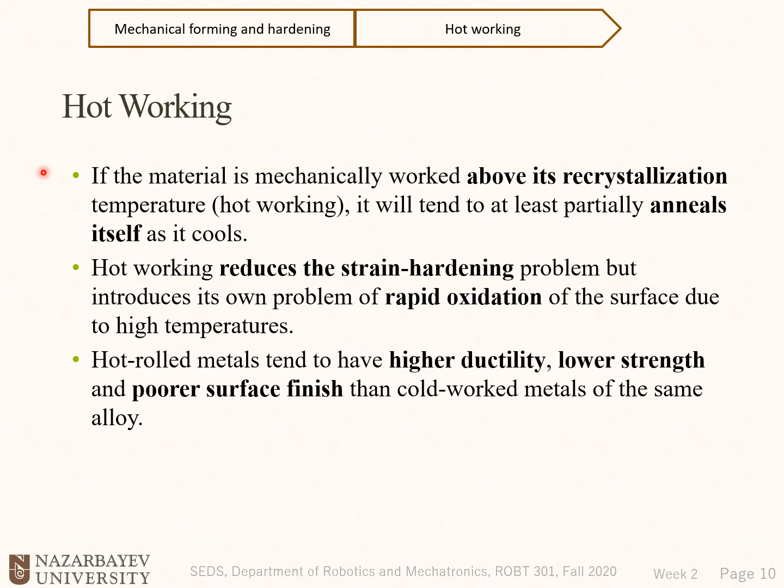Hot working reduces the strain hardening problem. Yes, so we had strain hardening issues with cold working. We couldn't apply so much stress on a part, otherwise the part could break in cold working. But in hot working, because of that self-annealing, we could reduce the strain hardening problem, but it introduces its own problem of rapid oxidation of the surface due to high temperature. So we have a high temperature, it will absorb oxygen at the surface,